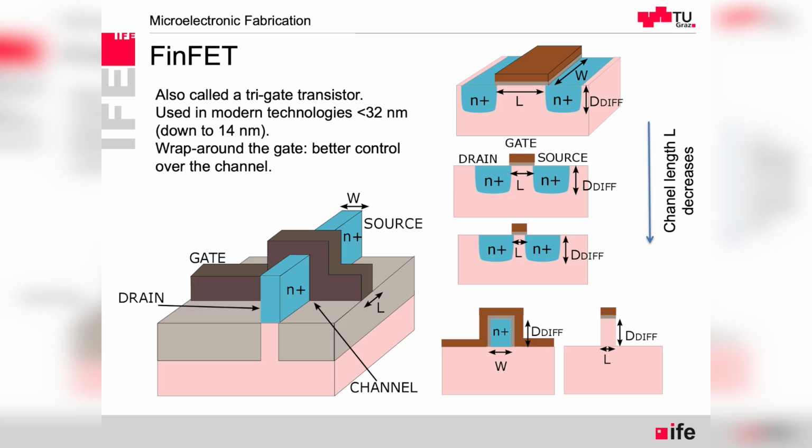What is shown here is not to scale, but still conceptually, we can see that the length is getting shorter and shorter, but the N+ region extends quite deep in the substrate. And at the bottom of the N+ region, we don't have control. The gate applied potential doesn't control what happens at the bottom.